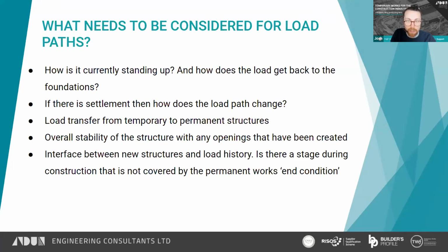Is there a stage during construction that is not covered by the permanent works end condition? And by this end condition, I mean that if you have a structure that is being conventionally constructed from bottom up with stability mechanisms such as shear walls and bracing being constructed with the structure, then the worst case stability case for the structure is going to be when the whole thing is completed, i.e. you've got maximum destabilizing lateral loads from wind when the building is tallest.